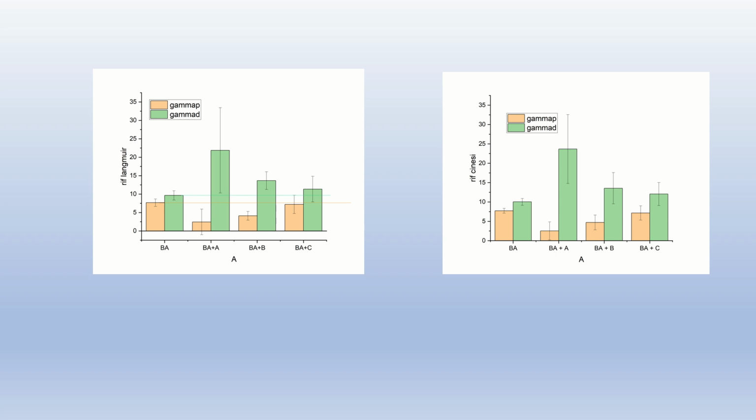For this reason we think that when I put this additive, the surfactant, in the bitumen, the interaction between surfactant and the stone changes the viscosity of the conglomerate, the final asphalt, because I repeat, it doesn't change the viscosity of the bitumen, but changes the viscosity of the asphalt. In this case, we can reduce the temperature of the road pavement produced.